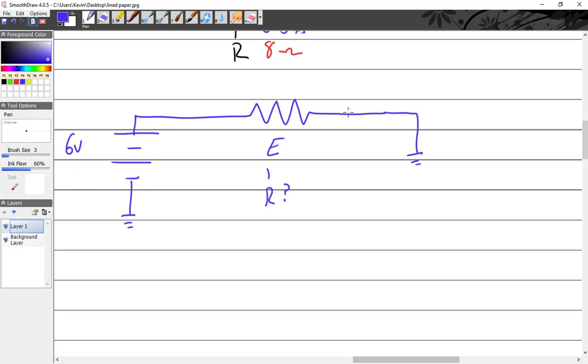All right, let's see. Add another resistor. That's what I'm going to do. Well, hang on. Let's talk about the resistance of the wire, just like I was talking about. I want to know what the resistance of this wire is, and so with no power on it whatsoever, I take an ohm meter. No power, so we have to make sure we have no power. And I put an ohm meter across it, and I say, all right, what is the resistance of this wire?